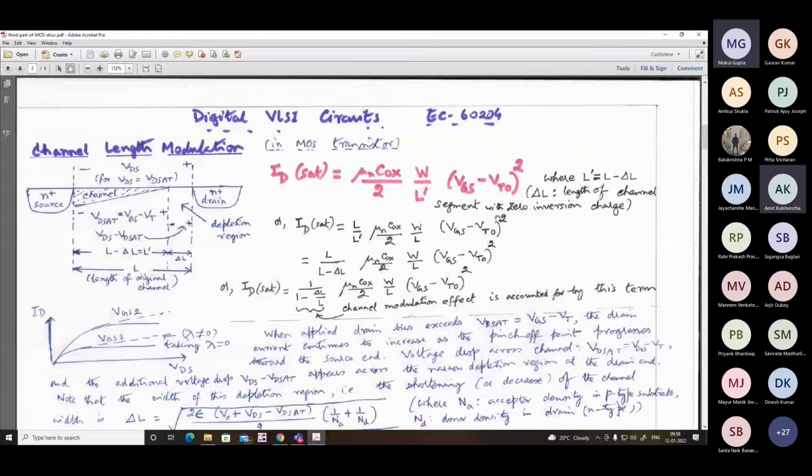Let us assume that, because on the circuit designer side, we cannot go deep into the device physics. I lose track actually, as you have to consider several statistics, like Maxwell-Boltzmann statistics, Fermi-Dirac statistics, Bose-Einstein statistics, all these things. Then the concept of density of states. So let us tacitly assume that for degenerate p-type semiconductor, EV and EF will be coincident, whereas for degenerate n-type semiconductor, EC and EF will be coincident. That will make the calculation easier.